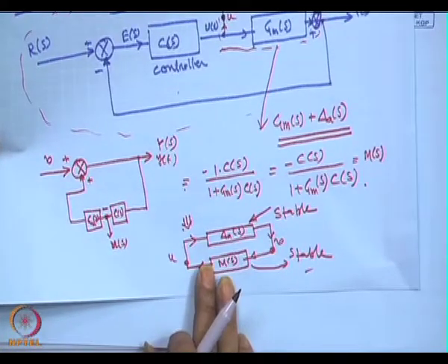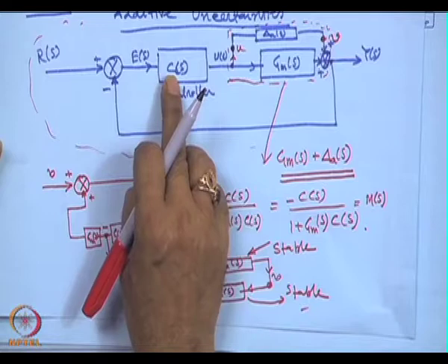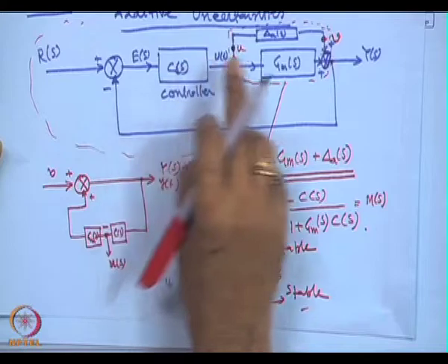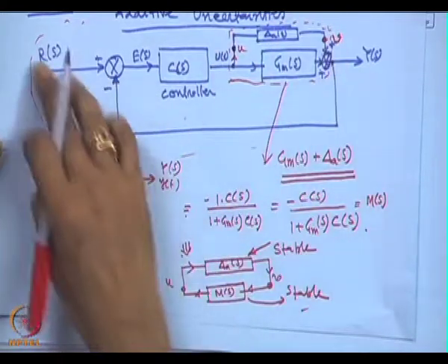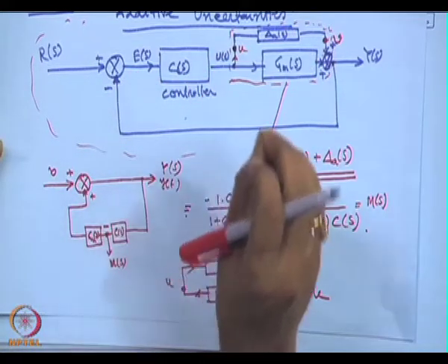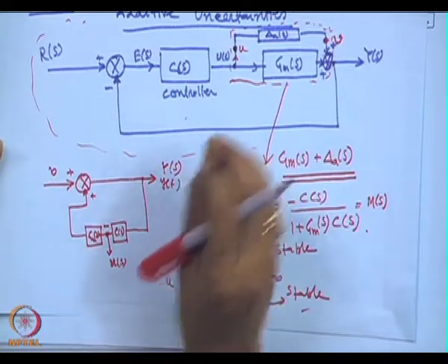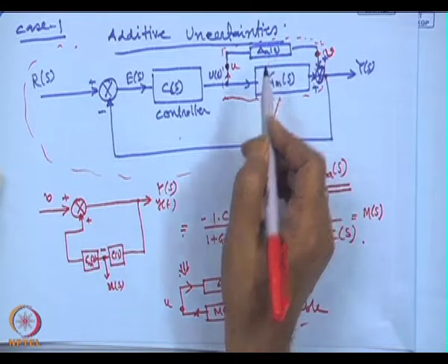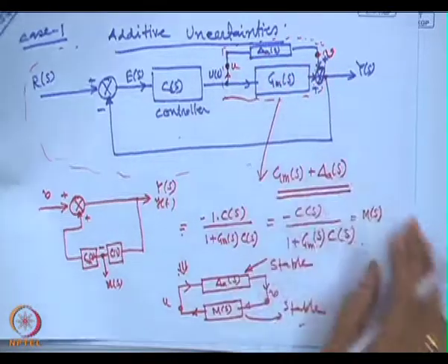So, this problem is now here: we have designed a controller C(s) based on the plant model. Then we want to see whether the same controller will be able to stabilize the perturbed plant or not. And if it is able to stabilize, how big can the perturbation delta A be so that the system remains stable?